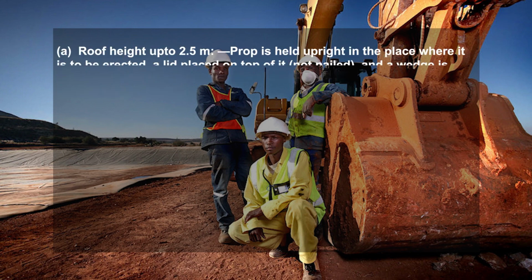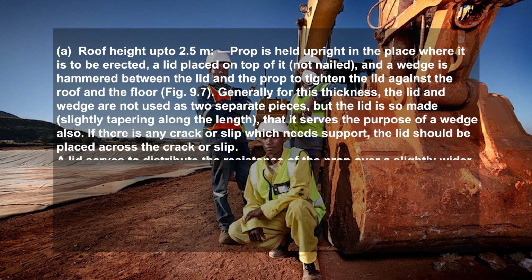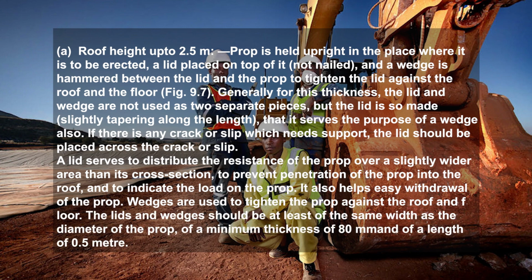First, roof height up to 2.5 meter. The prop is held upright in the place where it is to be erected, a lid is placed on top of it, not nailed, and a wedge is hammered between the lid and the prop to tighten the lid against the roof and the floor. Generally, for this thickness, the lid and wedge are not used as two separate pieces, but the lid is made slightly tapering along the length, that is, to serve the purpose of a wedge also.